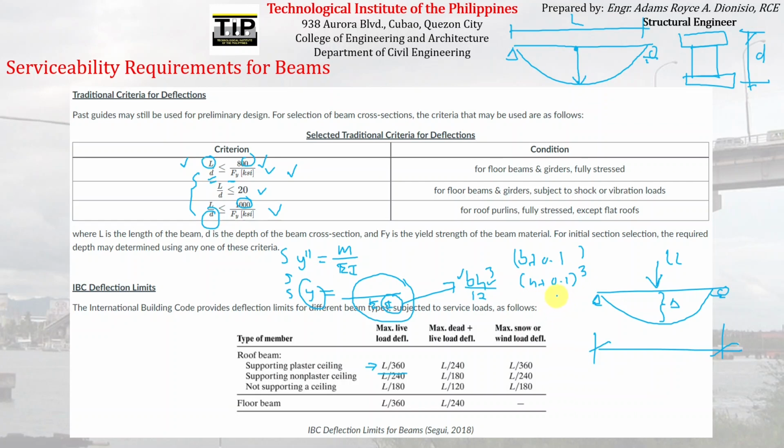So ilan technically yung magiging increase sa moment of inertia? Malaki. Kasi parang natitriple yung dinagdag mo. Nagdagdag ka ng maliit on both B at H, pero yung effect niya sa H, natitriple, kasi nga kinukube mo siya dito sa formula. Usually naman sa lahat ng formula ng moment of inertia, ganyan yung pattern nila. Yung total depth, nire-raise mo to a certain power. Square, cube, fourth, etc.